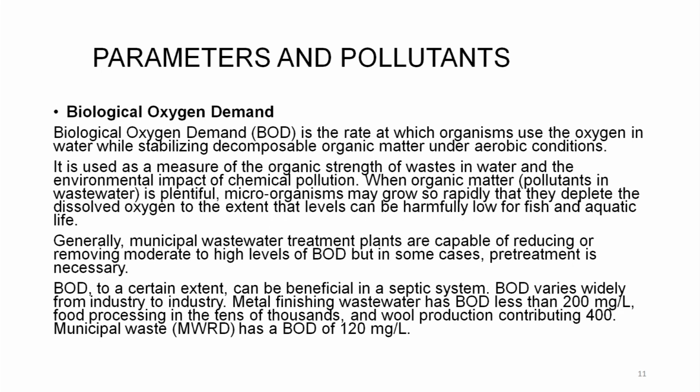Biological oxygen demand is the rate at which the microorganism use the oxygen in water while stabilizing decomposable organic matter under aerobic conditions. It is used as a measure of the organic strength of waste in water and the environmental impact of chemical pollution. When organic matter, that is the pollutants in wastewater, is plentiful, microorganisms may grow so rapidly that they may deplete the dissolved oxygen to the extent that levels can be harmfully low for fish and aquatic life.